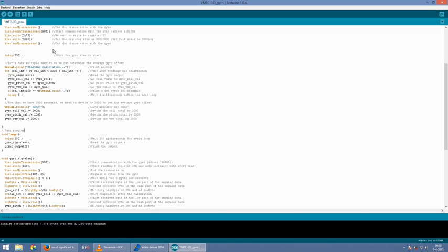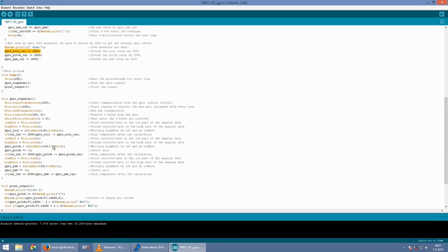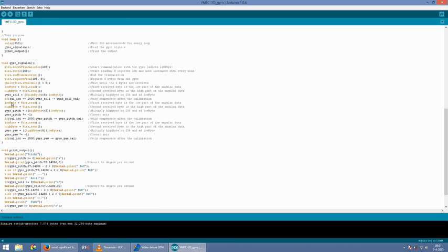The part that I added is this calibration part. Most gyros have a little offset that causes the multicopter to drift. Therefore, we take multiple samples, in this case 2000. After this, the sum of the 2000 samples is divided by 2000, so we can get an average of the offset. This offset is subtracted from every measurement and prevents the multicopter from excessive drifting.